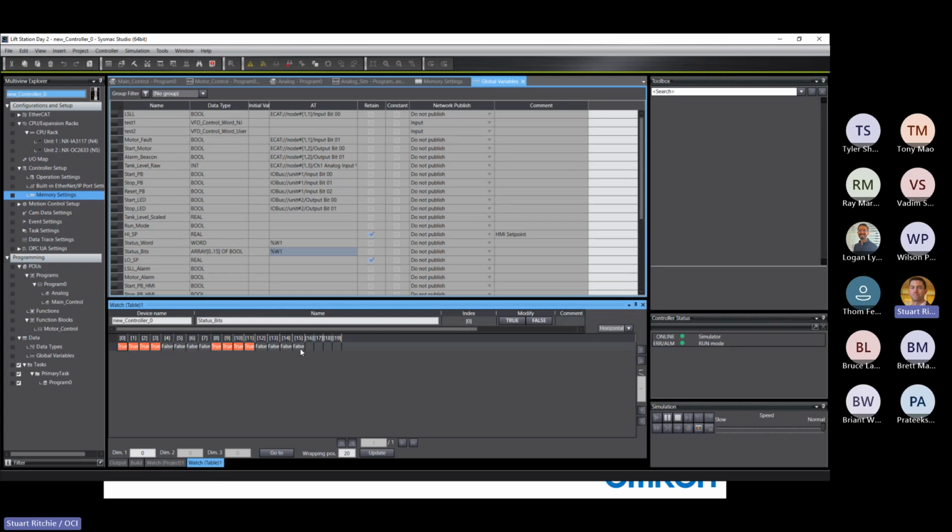So in logic, you could assign an address to an alarm word, for example. That's a common application for this. It comes in over Modbus as a word. It has bits that indicate specific alarm conditions in it. And we can have a rung below it where we take those bits and map them to the alarm bits that are required.